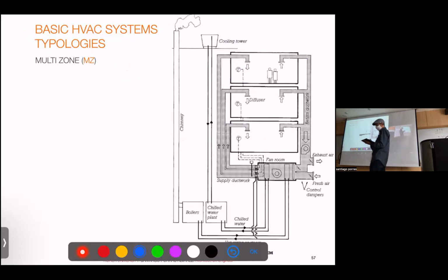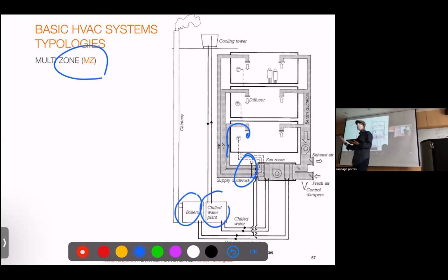Even more sophisticated is the multi-zone. This is a system in which you have not only the air, but you can regulate the temperature, how much exchange you have. And the most sophisticated, you can even choose if having cool or hot, which at some times of the year you may find necessary, right? That means having boiler and chiller working at the same time. So it's not very efficient, but very high quality facilities like hotels also need to give the facility to use all of that, right? You have individual ducts, which means much more expensive, much more space, much more difficult to make.